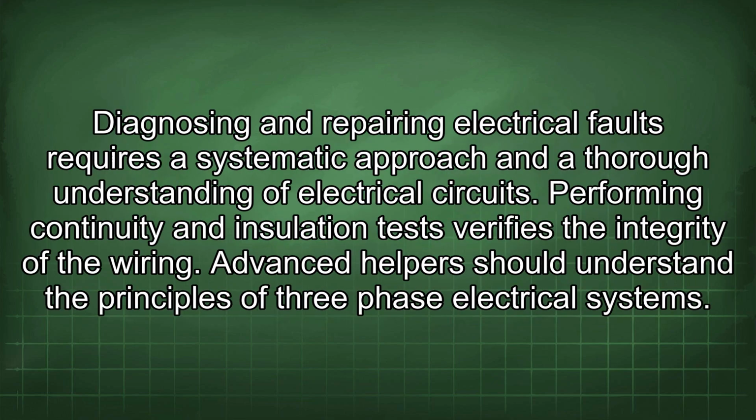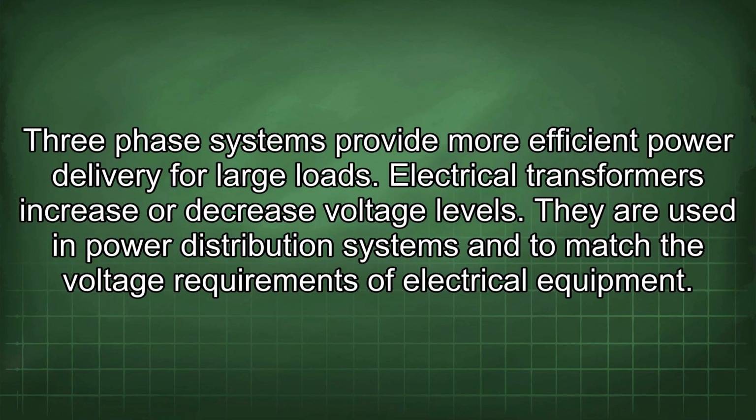Diagnosing and repairing electrical faults requires a systematic approach and a thorough understanding of electrical circuits. Performing continuity and insulation tests verifies the integrity of the wiring. Advanced helpers should understand the principles of three-phase electrical systems. Three-phase systems provide more efficient power delivery for large loads.